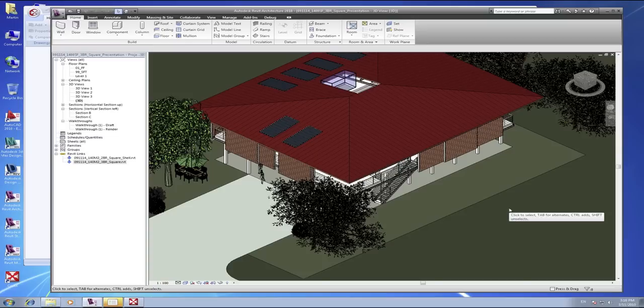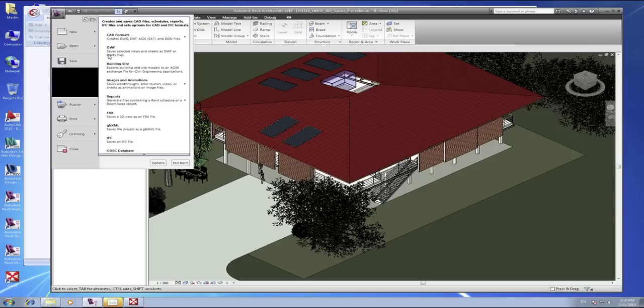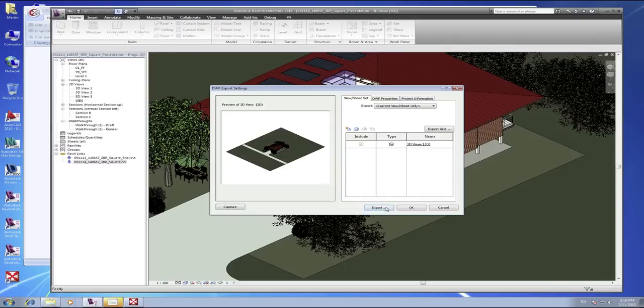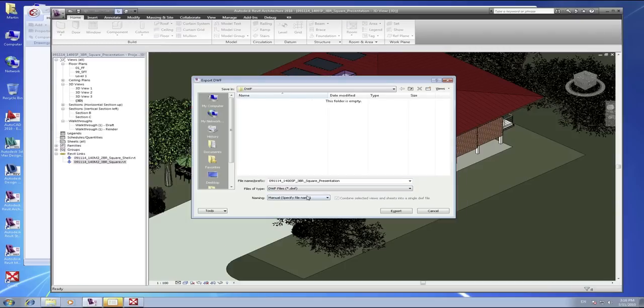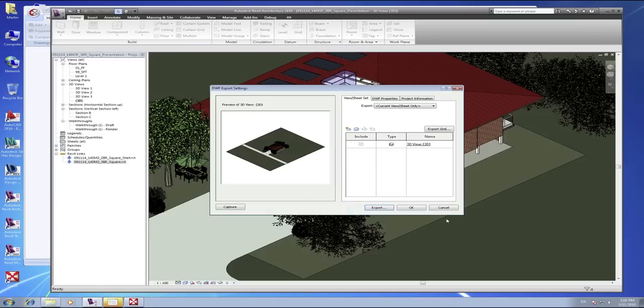And the first thing you need to do is export to DWF in order to use that DWF as a basis for your CostX data. So I'm going to the Export DWF dialog, click on Export. It's important to select DWF and not DWFX because CostX cannot read DWFX at the moment, and export to DWF instead. I've already done so that we don't have to wait for the export to commence, and basically we can simply cancel out here and turn our attention to CostX.